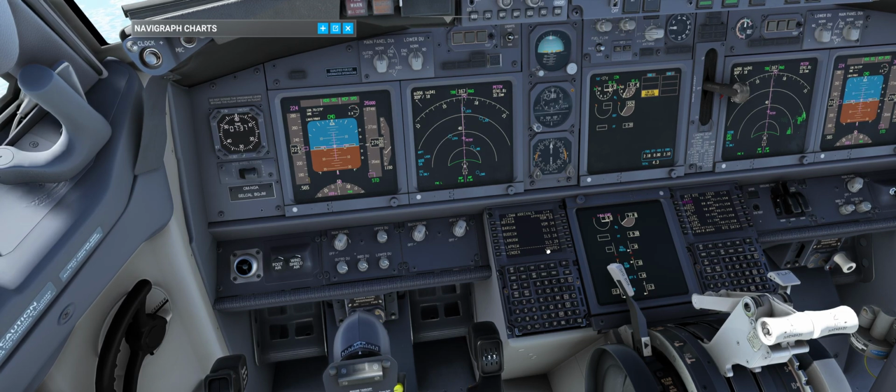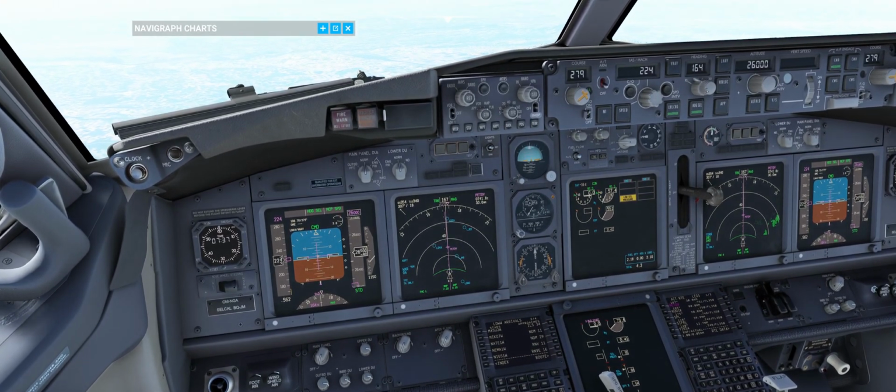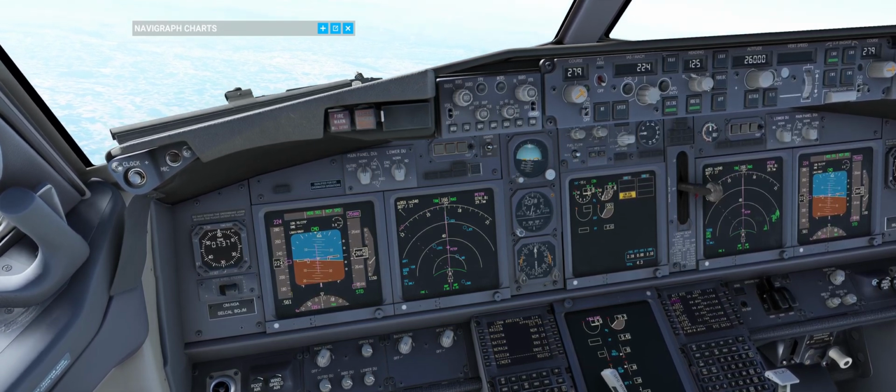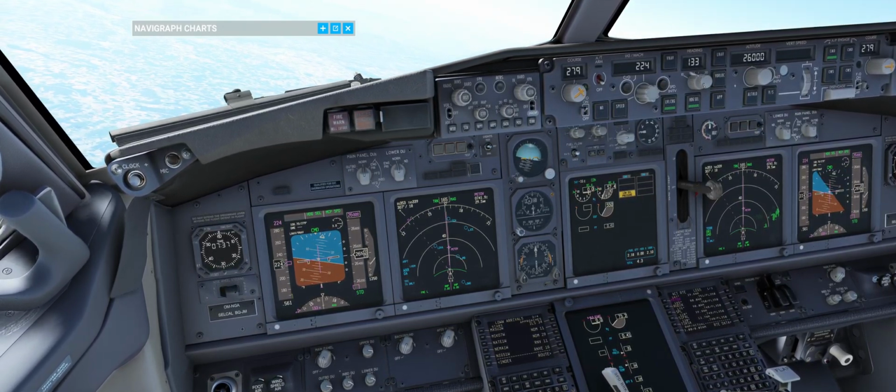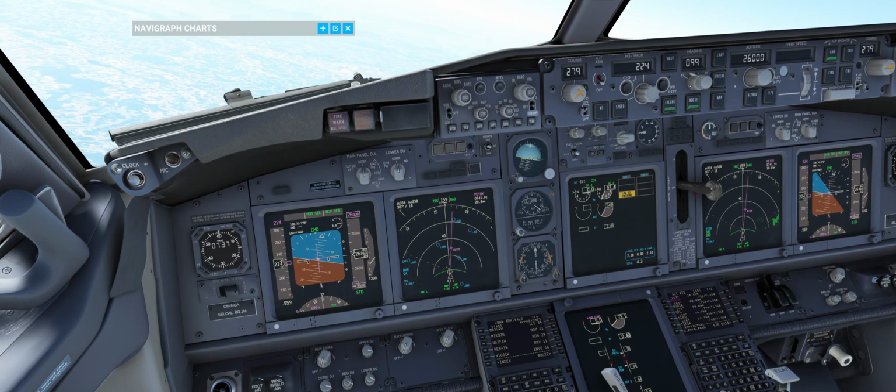Fire assistance, fire category is okay, valid for us. Medical services are at Vienna Airport. Everything is right there, so we can land at the Wien Airport. So you can pre-select with your air traffic controller the waypoint, or you can start the turn. I suggest to start the turn with heading select with a bank angle of 15. It's more or less okay. You can turn with a bank angle of 25.